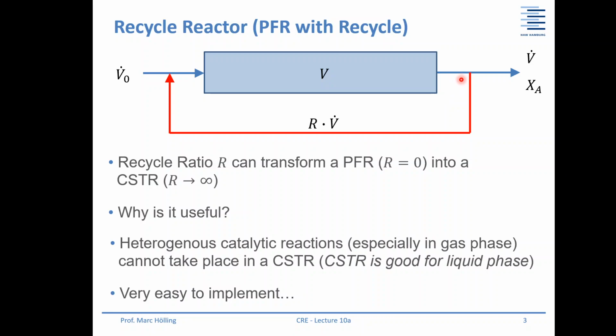So here you can find a very simple layout for how you can transform your plug flow reactor into something like a continuously stirred tank reactor. Of course, in reality you won't go for the recycle ratio up to infinity, but you can find a solution somewhere in between.